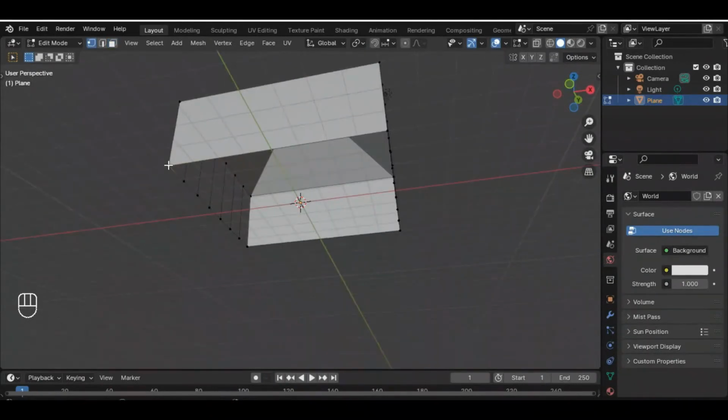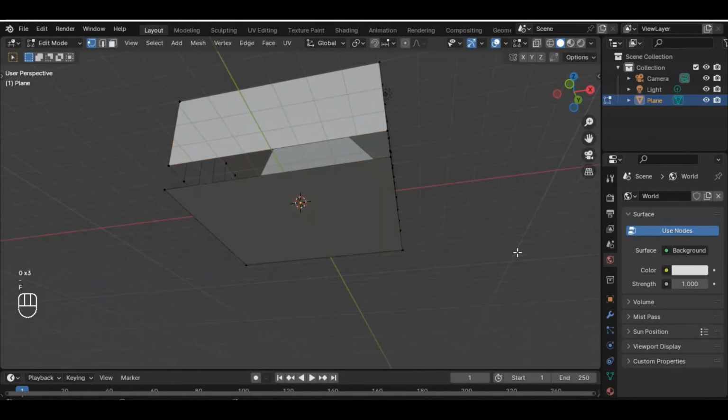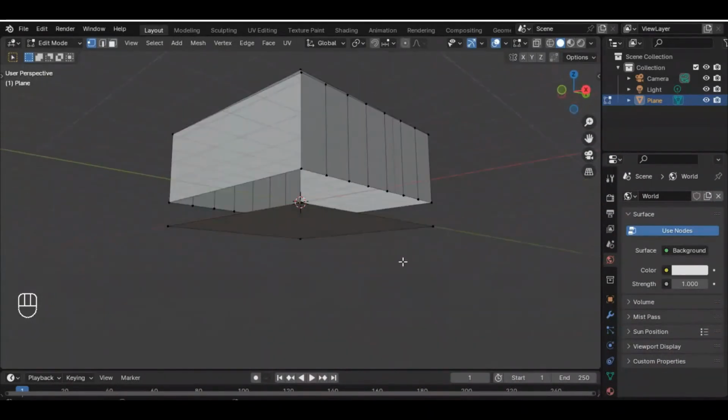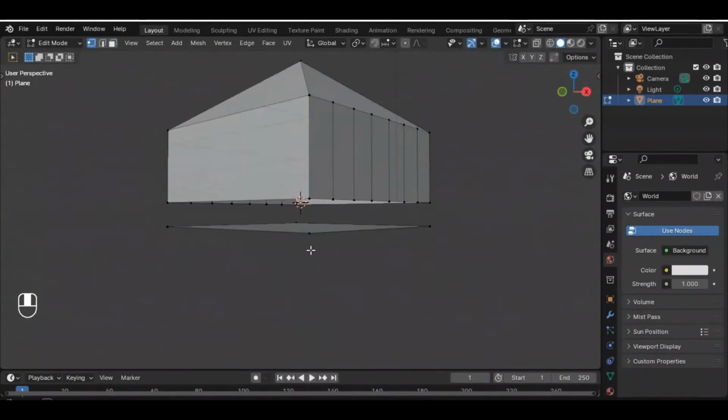But before I delete this one, I can go here to my vertices to create a duplicate of it that will be independent of what is existing. So Shift D, Y, Z. Let's go Z 1000. So let's create a face there. So now we have this face here. So this is what we want to achieve.